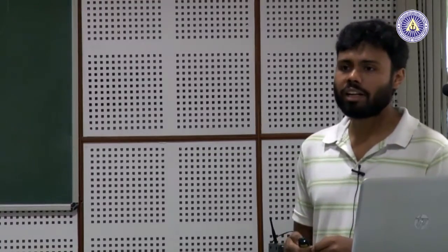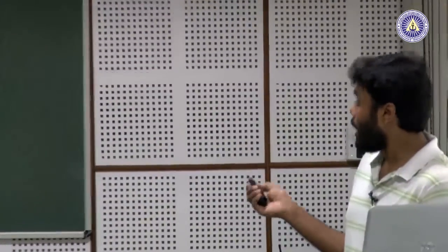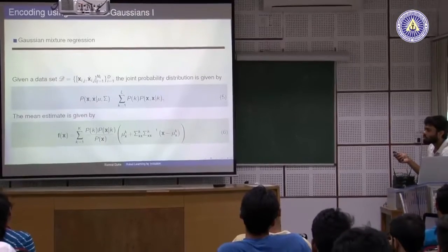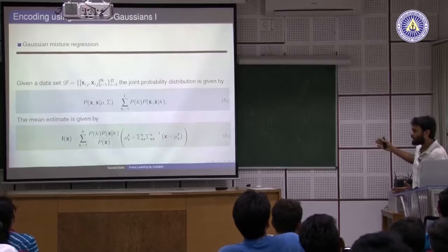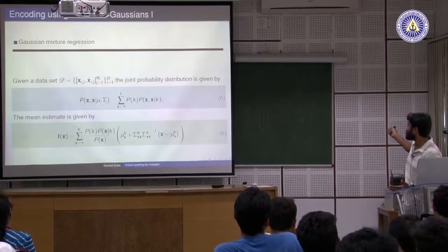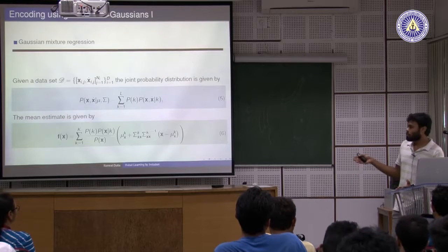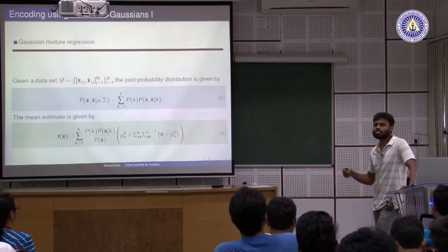What you do is you learn it in joint space. You try to capture how the joint space trajectories were demonstrated, and you learn that motion. And it has a time dependency, as I showed using that canonical system. It always goes from 1 to 0, so the time it takes during the demonstration, all the motion has to be completed within that time framework. So DMPs have these limitations.